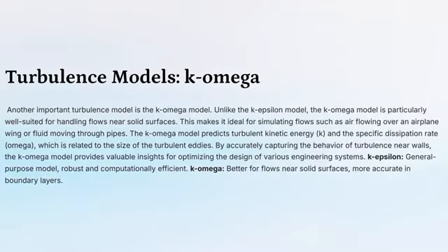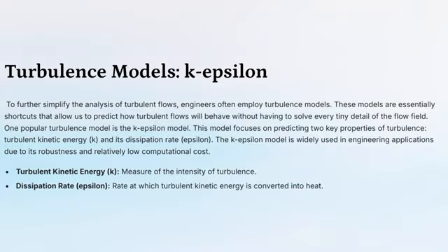It's better at understanding flows near solid surfaces, like air flowing over a plane's wings or fluid moving through a pipe. And another model is the k-epsilon model. It focuses on predicting the turbulent kinetic energy and how quickly it dissipates. Super useful in engineering applications.